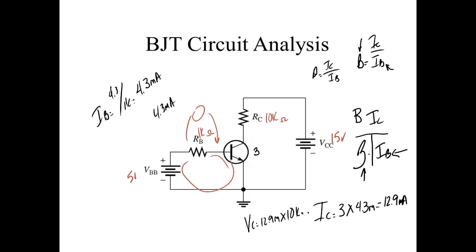Once the transistor's saturated, it's saturated, right? You understand that? So if the transistor has a beta bigger than minimum, it's not going to hurt anything. It'll still saturate. What we're trying to do is make sure it saturates in every situation you could be in, whether it's running in Alabama in the summertime or up in Adak, Alaska, right?